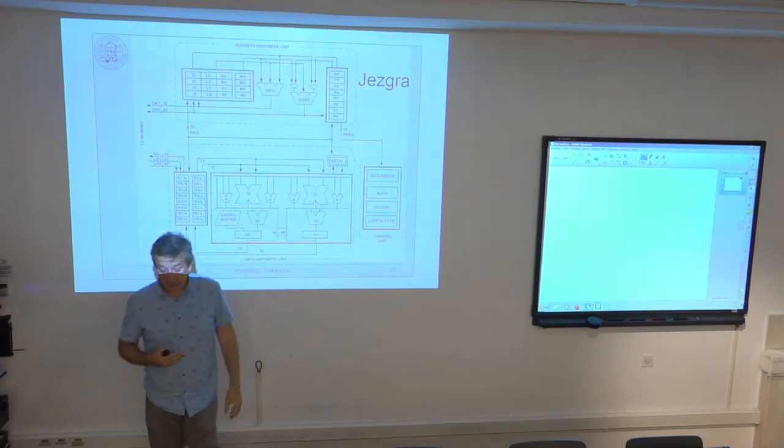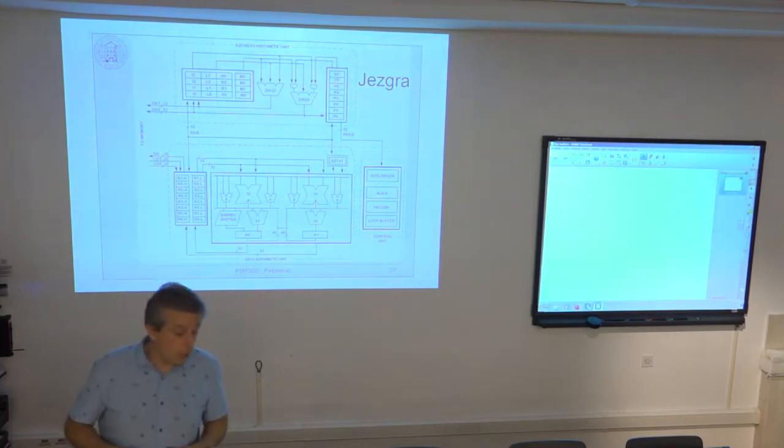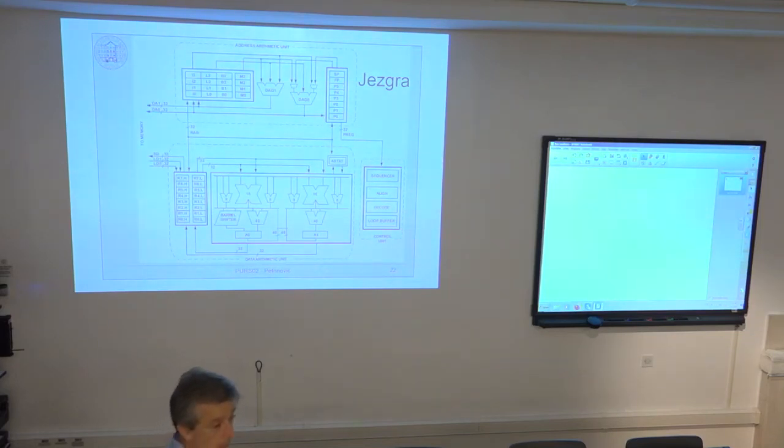So that is the way that it can support two multiplication instructions in the same cycle, because it has two 32-bit buses to take actually four 16-bit values as arguments for multiplication and accumulation. It is the same as with this simple architecture. The arguments cannot come directly from the memory. So they must be prefetched into these registers with a fetch instruction. And once these are here, I can use them as an argument for multiplication or ALU operation.